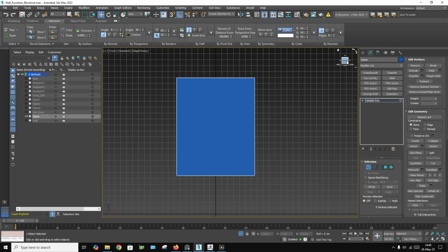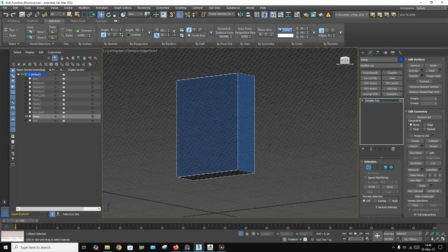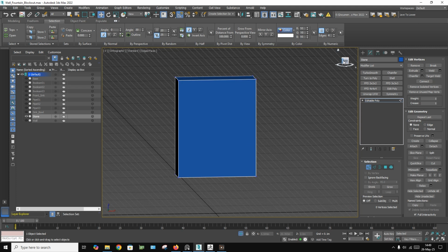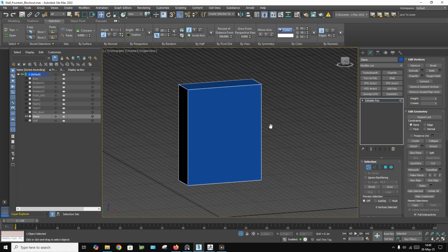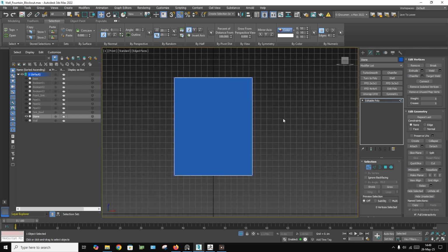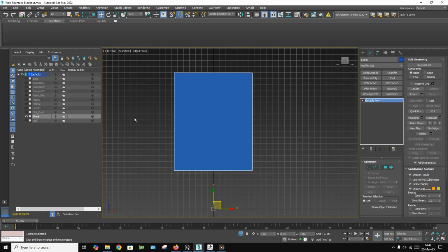We are doing this so that ZBrush won't run into any problem, because the connection of all of the vertexes is very important for ZBrush. Any unconnected vertex or unconnected edge inside ZBrush, the mesh is going to seriously run into problems, and it is going to give us enormous holes. We don't want that, and we don't want any black part on our object like that. So we are going to weld them. After welding, let's select our object, and we only want our stone here.